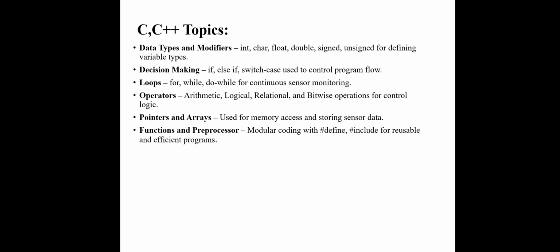This project heavily relies on embedded C programming to define all logical and control operations. I have used various concepts such as data types and modifiers to define variable size and ranges, decision making statements like if else and switch case to handle control logic, and loops like for and while to continuously read sensor data.